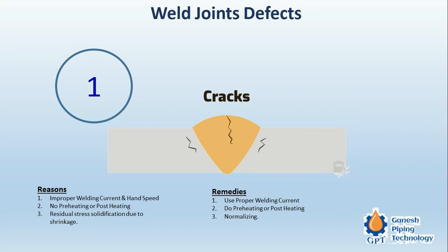Why? Because when we are welding thick plates, like for pressure vessels, especially in nuclear projects, the shell thickness or the pipe thickness is comparatively higher, like 4 inch, that is 100 mm or maybe 150 mm thick plates, which are being welded together for hemispherical pressure vessels. So in that case, we have to go with preheating and post-heating.